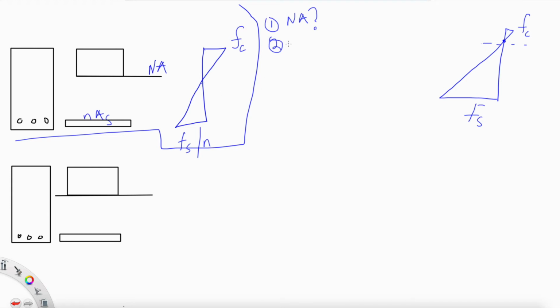Second, we have to calculate something called the first moment of area. What does it mean? We took it in statics, that's really basic engineering. That means it's the area of a section multiplied by the distance of its centroid to the neutral axis. We'll see it in the calculation.